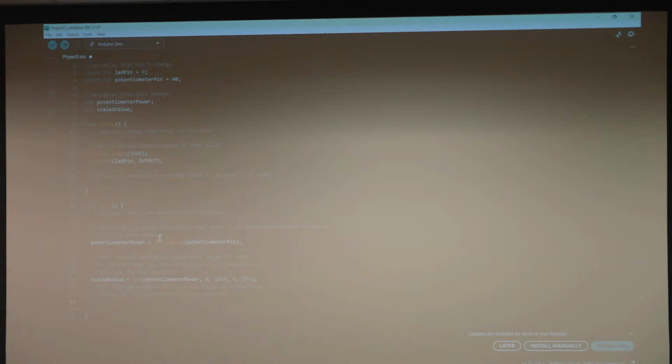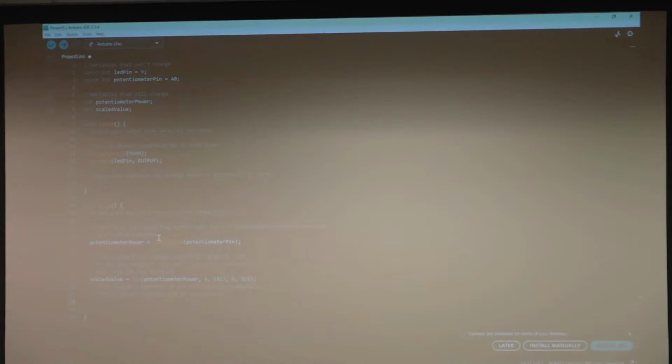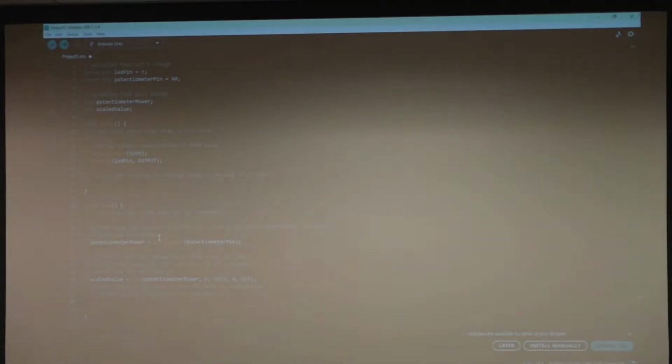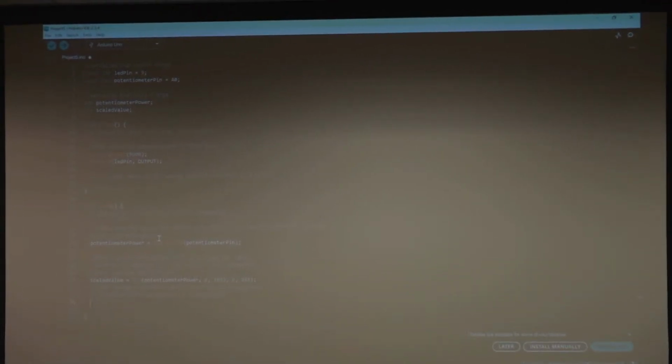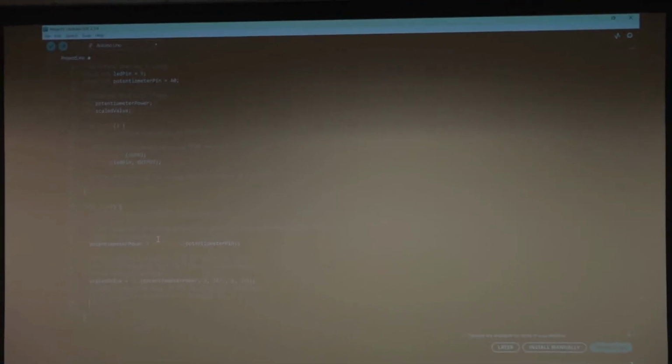Serial.print with parentheses, double quotes, analogRead. Serial.print analog data, okay, yeah, that's for debugging. But to turn on the LED, what function do we use? Similar. So we should use analogWrite, but how? Why a for loop? That's if you want to do it dynamically with programming, but we are doing it dynamically with the component.